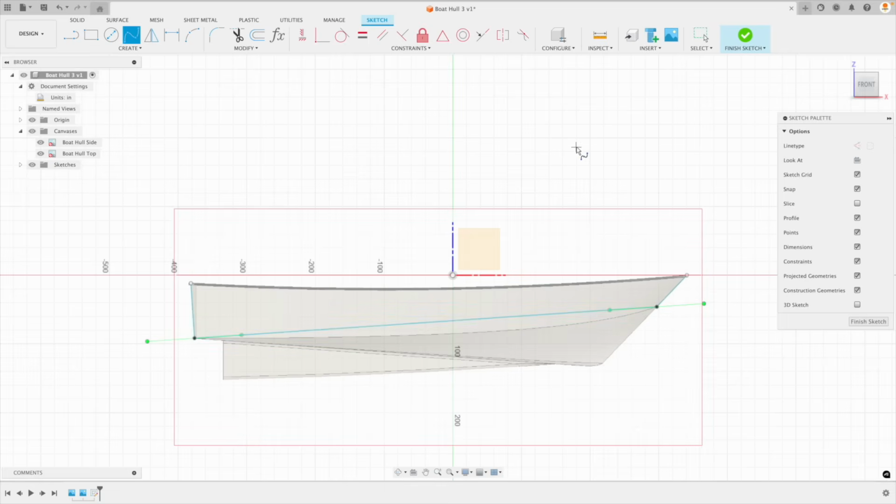Now, I'm still in spline mode, so don't pick this handle. Press Escape, and look what happens when I press Escape. It goes back to my regular mouse cursor. Now I can grab this control rod right here, and you can push it and pull it. You can do whatever you want, and I'm going to try and line up. Oh, it was pretty easy. Look at that. I'm just going to line up that spline so it follows that profile of the boat.